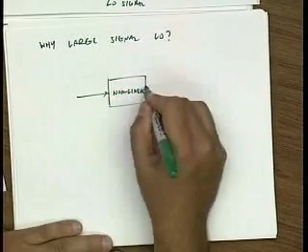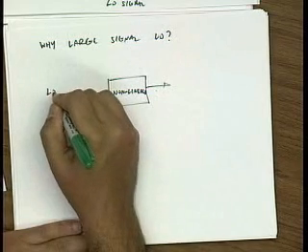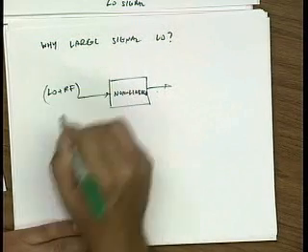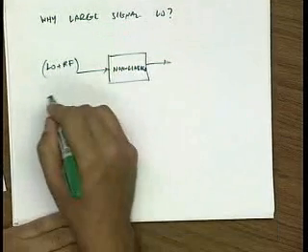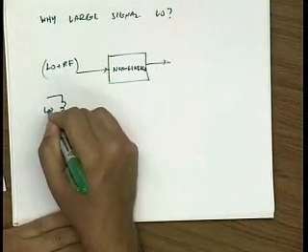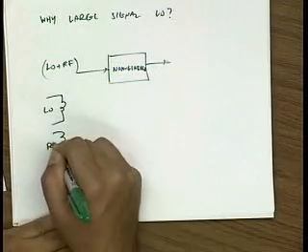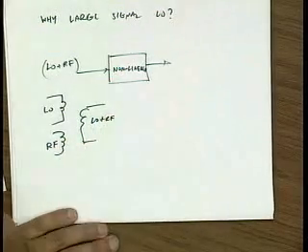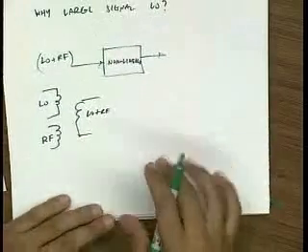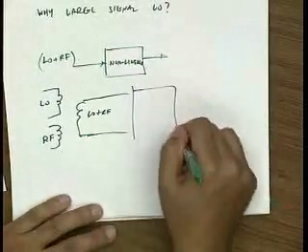And if I just sum my LO plus my RF, somehow or another, maybe I use a transformer, so I have my LO, I have my RF, and I take the sum, or I might do current domain summing, and then I apply it to some nonlinear function.